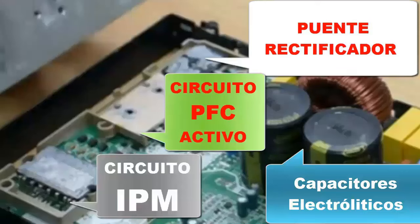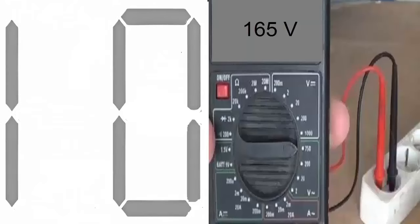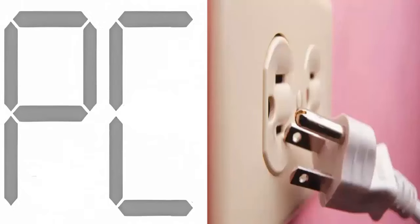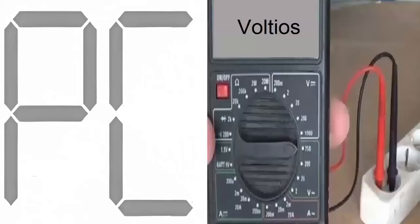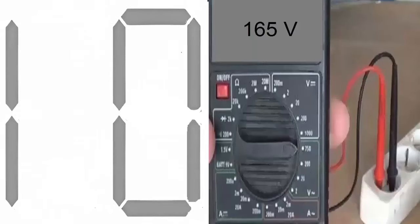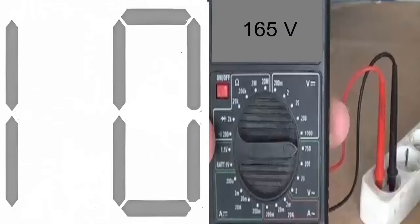Let's look at the steps to solve the PC10 error. A. Turn off the unit and disconnect it from the power supply. B. The first step is to check the voltage. To do this, use a multimeter on the AC voltage scale. Check the voltage value coming from the external power supply. If the voltage is too low, this is likely the cause of the error.